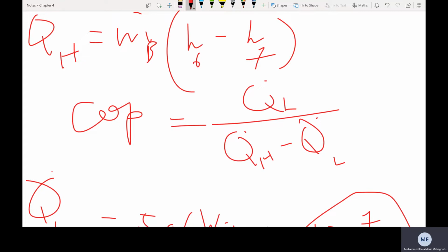Yeah, I know it is a bit long, and you feel like there are so many steps, but if you were doing it on paper yourself, you will see it's really nothing. You are solving the cycle much faster than if you were solving a Rankine reheat cycle. Believe me, you don't have any processes to do from 7 to 8 and from 3 to 4, and that's directly the throttling device or the expansion valve. So it is much quicker.